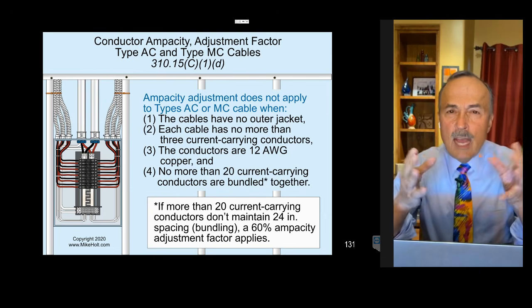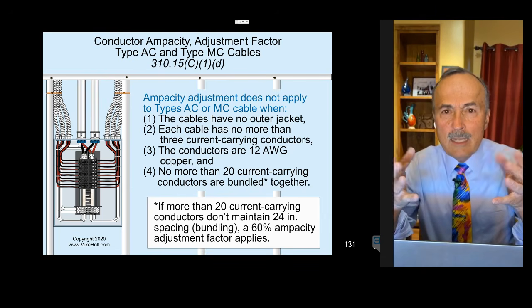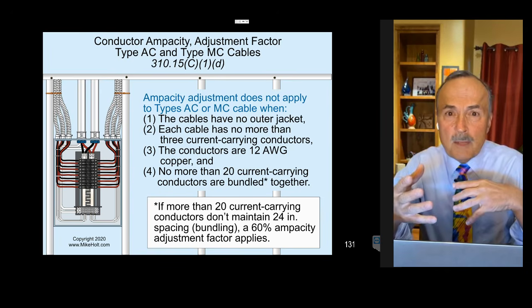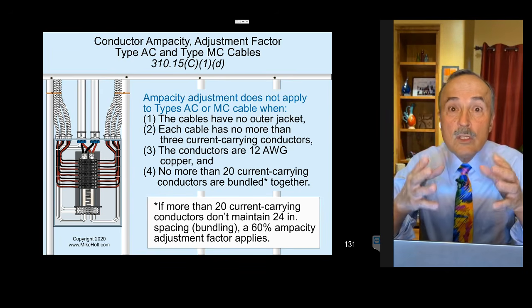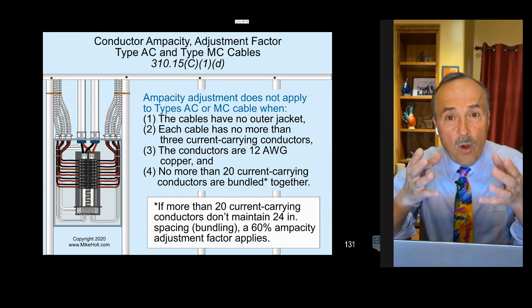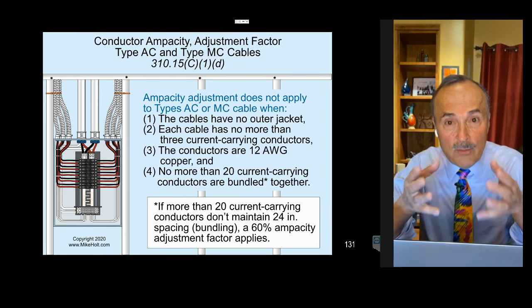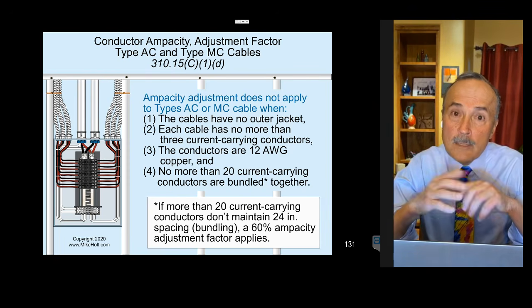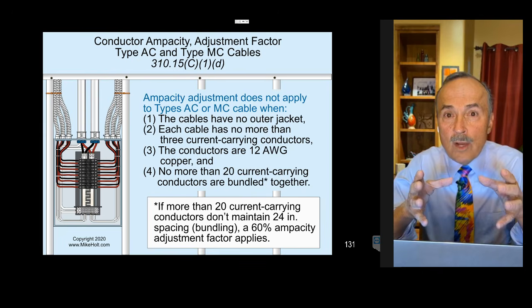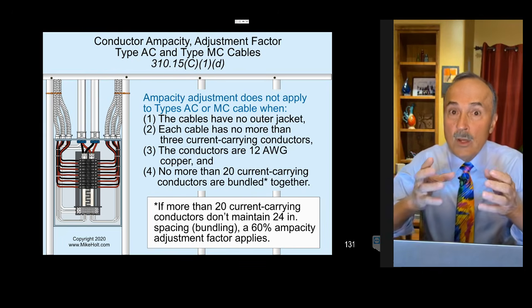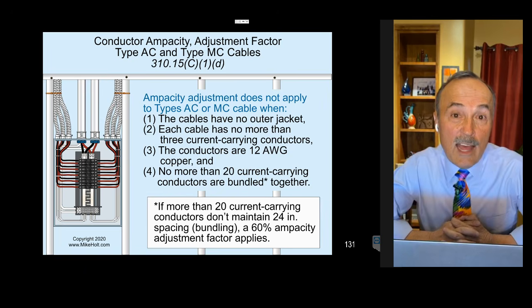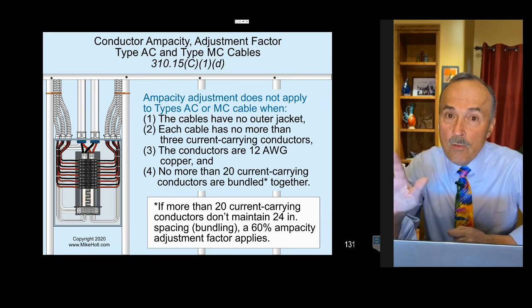And people were saying you have so much information in Article 310 that it confuses people when it's under 1,000 volts. So can you do us a favor? Can you get all the over 1,000 volt information out of 310? They said, good idea. So they moved all the over 1,000 volt information in the 2020 code into an Article 311 that I can purposely ignore, because the scope of all my programs is 1,000 volt systems and less.